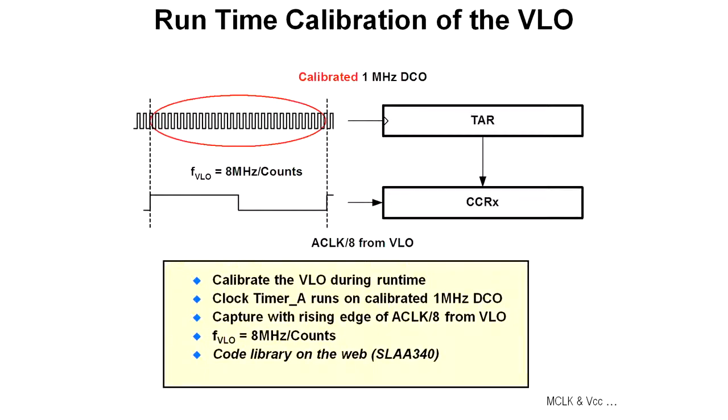So if you're looking to get crystal type accuracy from the VLO without having to pay to have a crystal on the device, here's a way for you to minimize the amount of extra parts that you're putting on your board.